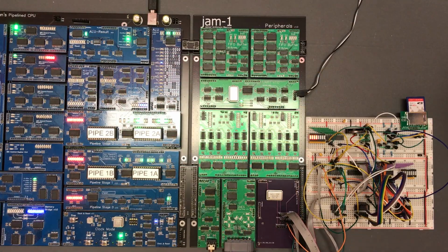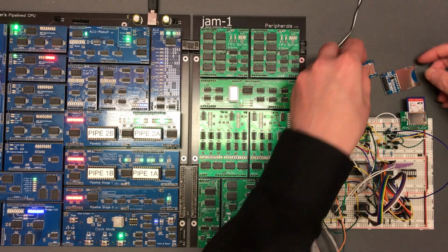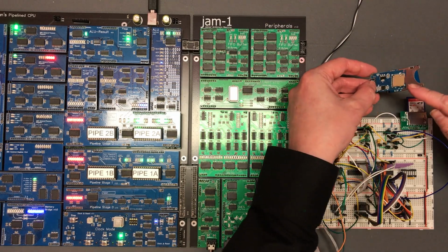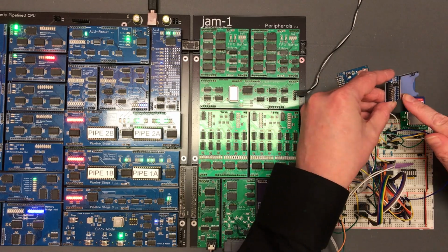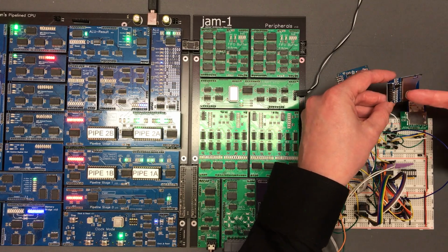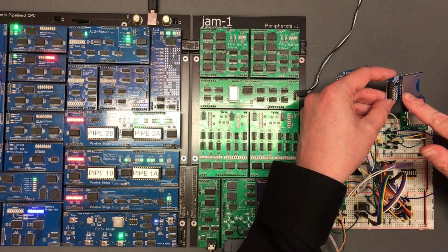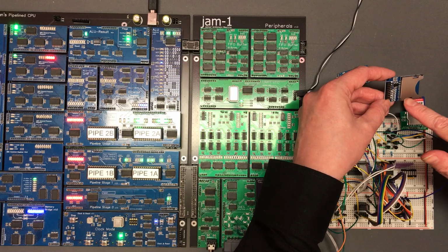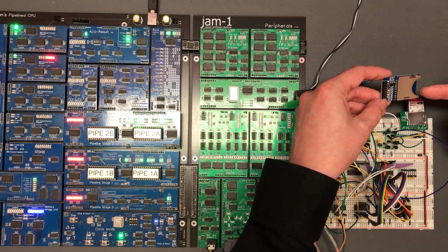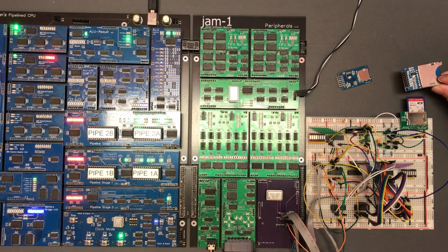Okay, back to the main channel for the final conclusion, but I would mention just while you're here that if you don't want to mess around with this circuitry, there are modules around like this which do the level conversion and allow you to plug an SD card in. This one's for micro SD. And be careful of these. This one's for a full-size SD card, but the logic here is just a few resistors, and I don't think it's quite as complete. I think it relies on the output lines being open collector, and so this is more suited to a microcontroller than the kind of circuitry I've built here. So I don't think you want to be trying one of those.